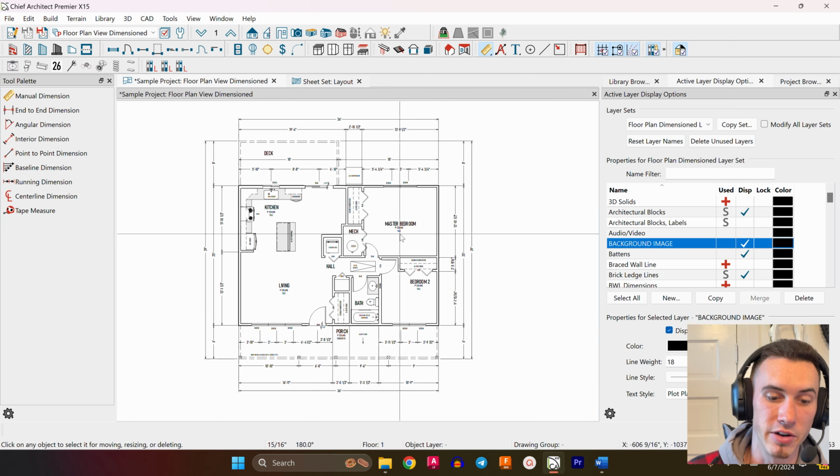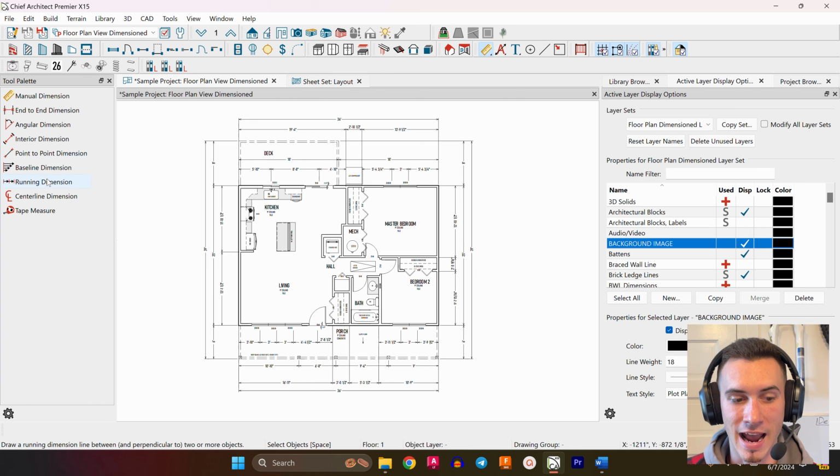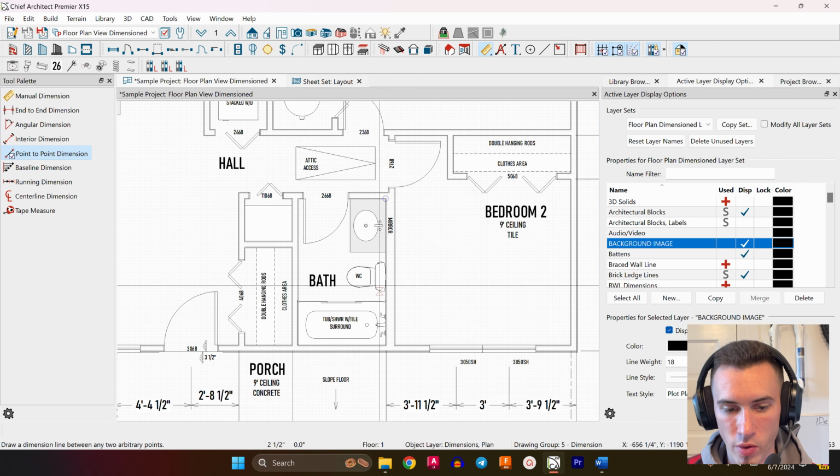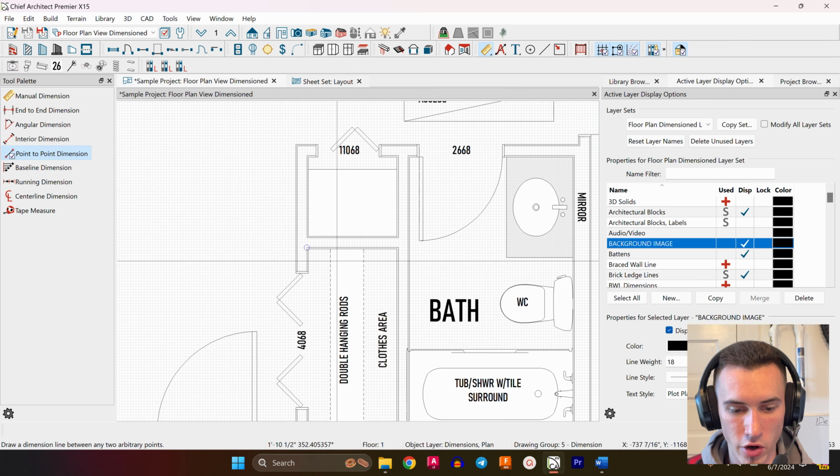Now we got to do the interior dimensions. Now the whole point of the interior dimensions is to tell the framers where to put these walls because they're not defined right now from the outside of the house. We have to add extras. Starting over here, I know where this wall is because it's dimensioned from the outside. I know this wall, I know this wall. I don't know the depth of this closet.